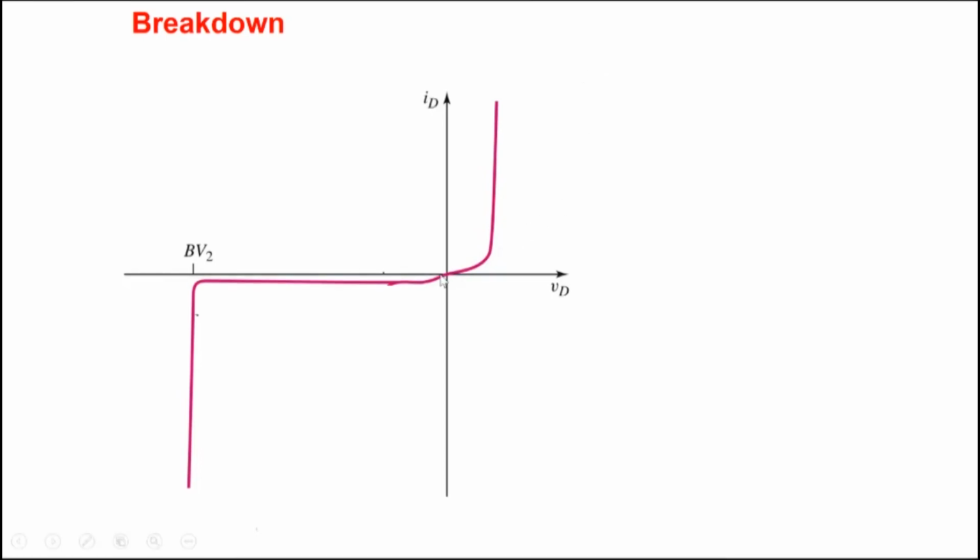Here we are showing that the reverse bias current is constant and equal to the reverse saturation current, but only up to a point. If you keep on applying higher and higher reverse bias voltages, eventually a phenomenon called breakdown occurs, and the diode starts carrying a large amount of current. We say that a breakdown has occurred in the diode here.